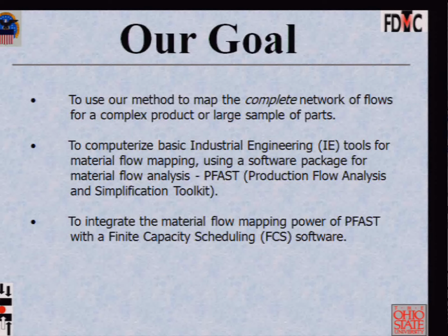Now, pull scheduling is not necessarily the only scheduling method. You can do finite capacity scheduling, you can do CONWIP, constant work in process scheduling, you can do drum buffer rope scheduling. Point again is that once you have designed the layout for flow, even in a high mix environment, you have to do something as regards scheduling. And so that's what my bias is. I'm completely aligned with finite capacity scheduling methods to do essentially resource constrained release of work into high mix environments, primarily driven around due dates and finite constraints at bottleneck resources.